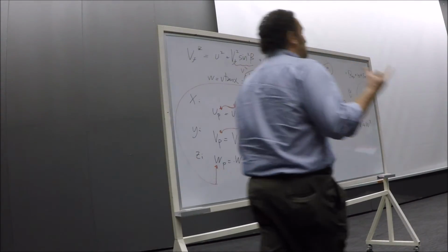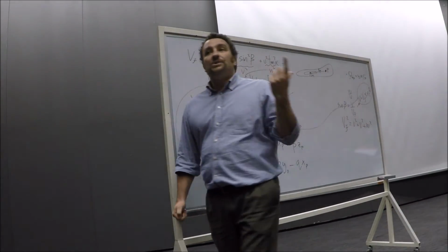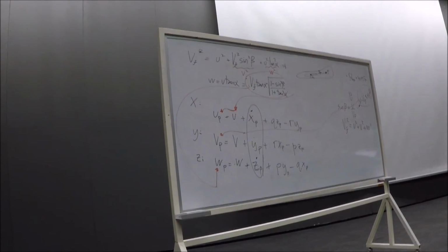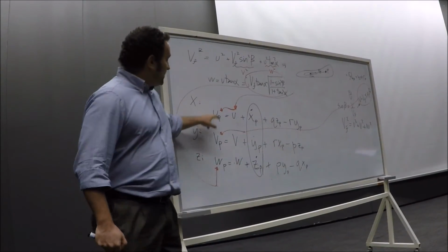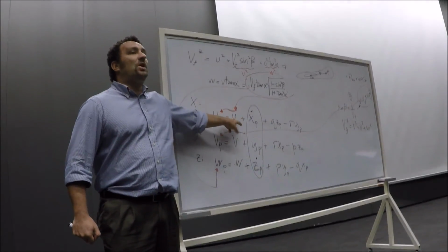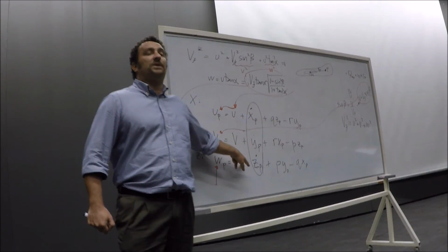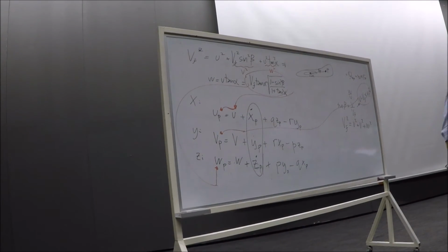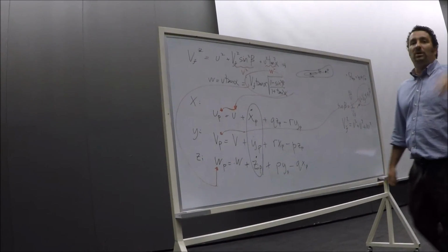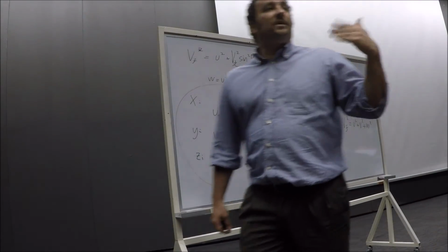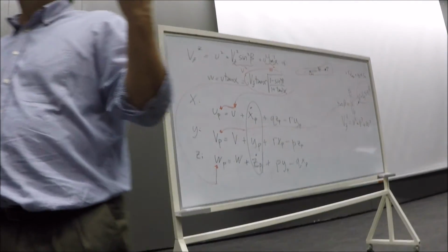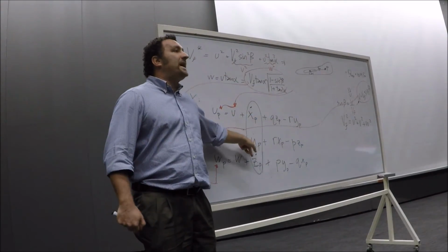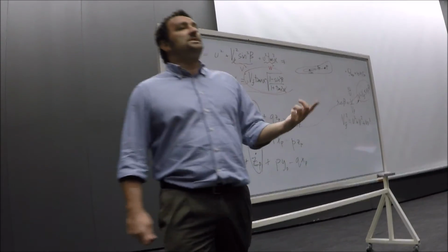So even though it may be a very small change, you may need to account for this to have an accurate measure of the aircraft velocities U, V, W. If you have this probe sensor, located for example near an engine, where there is a lot of vibration, this will lead to values for x dot p, y dot p, and z dot p which are not zero.